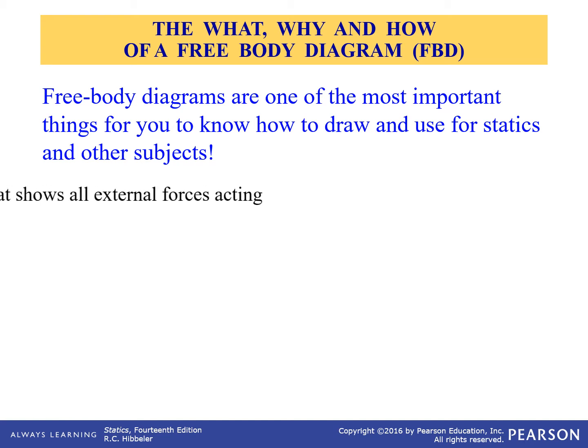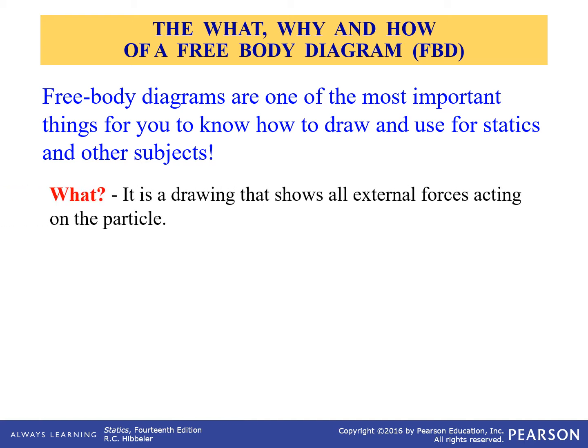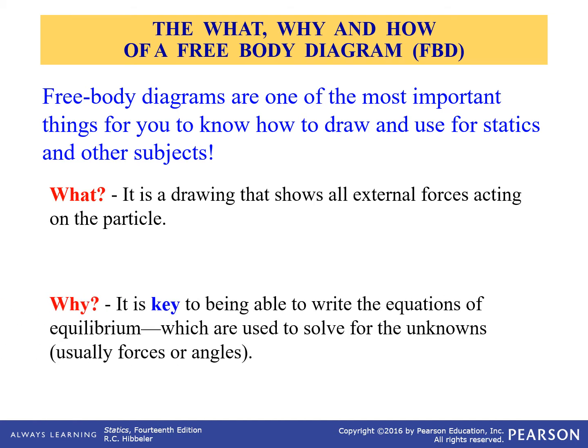So how are we going to do that? Well, essentially you would draw a free body diagram. For a free body diagram, we're going to take a point or a particle and consider all the forces that are acting upon that point or that particle and cut it out of the original system. We're going to do that so that we can apply our equations of equilibrium. You'll see EOE in the book and in the slides for the whole rest of the semester. EOE is equations of equilibrium. We are going to take those equations and solve for the unknowns so that we can figure out what the problem's asking for.